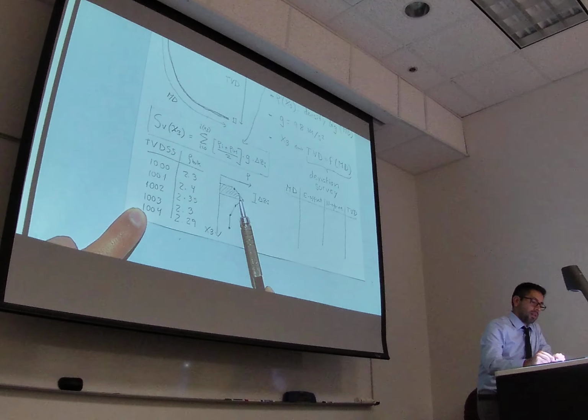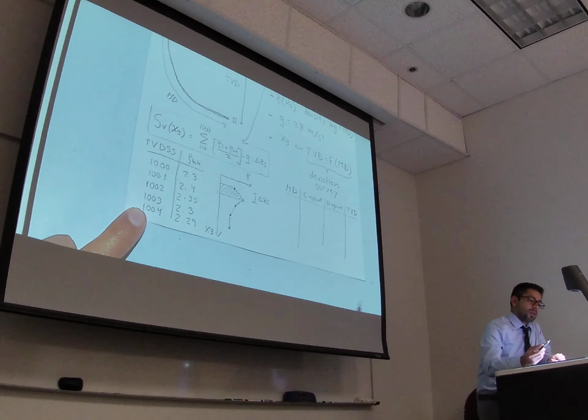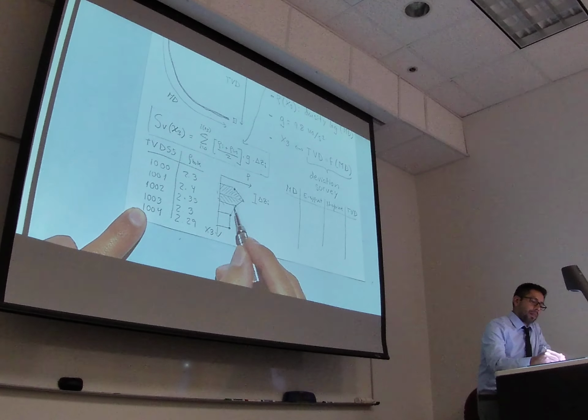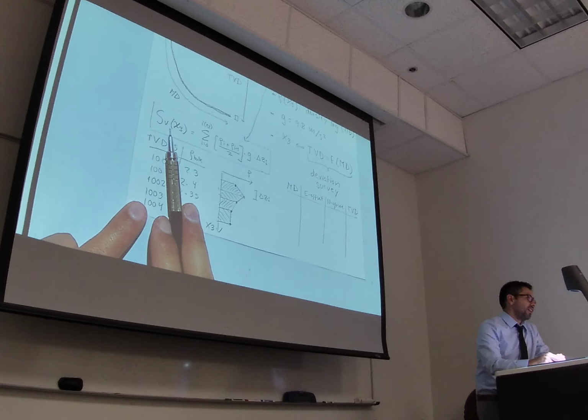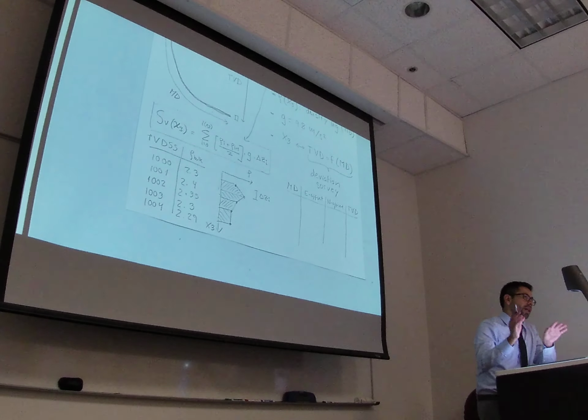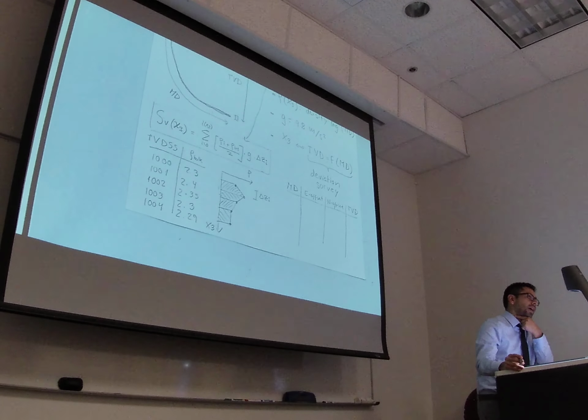And that one times the base of this trapezoid is just going to give you the area. So you add up all of these areas and you multiply by G, and then you're going to get the vertical stress. Make sure that your units are consistent, okay?